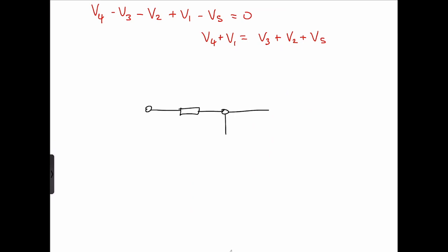Let's just connect it like that. A branch represents a single element, such as a voltage source or a resistor. In short, any two-terminal element. So here we have a two-terminal element, and it represents a branch. A node is the point of connection between two or more branches, at times indicated by a dot between connections. In this case, we can make this our node, which we can call N1. So that's a node. Then we can create loops.